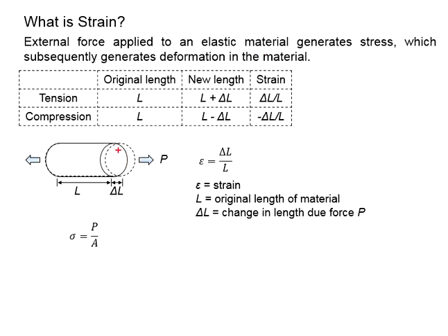Now, when the material is subjected to stress, it undergoes deformations. The pulling force will cause the material to elongate slightly. While elongating, due to the Poisson ratio, the material becomes thinner. Now, the original length is L. The elongation is considered as delta L. Under tension, the new length will be L plus delta L. The material now is slightly longer than the original.